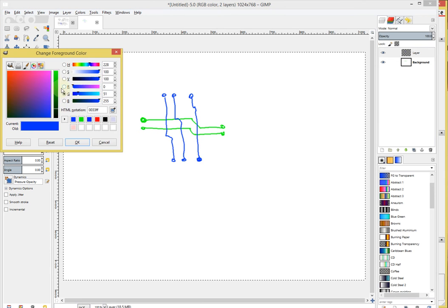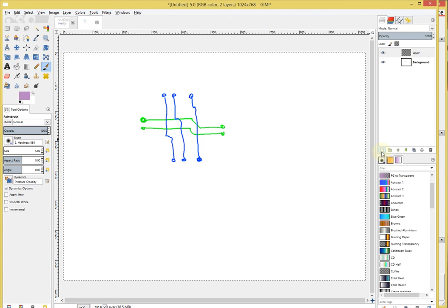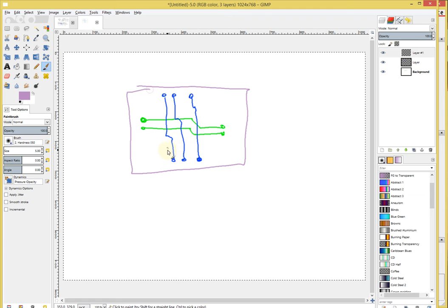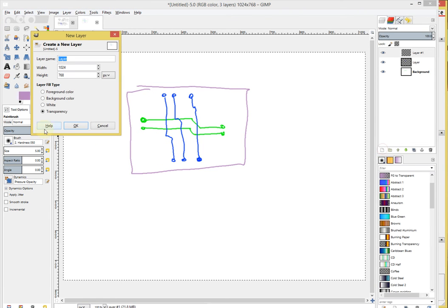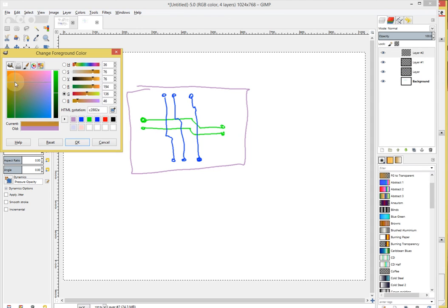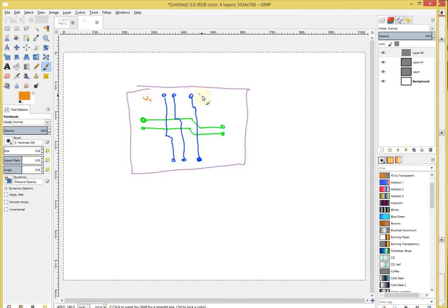Okay, then we have another layer. Let's say, make it that, and you have the solder mask, which is on top of this layer to protect the whole board. Then you have another layer consisting of the reference designators. Right, so you have U1, U2, U3, maybe little graphics that show you how to place things, etc. Anyways, each of these layers will generate a Gerber file separately, only containing that information.